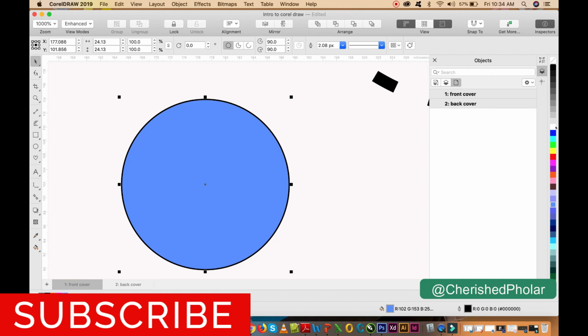If I want to change the color of the borderline, I come on the particular color I want, remember that this is being highlighted, then I'm going to right click. I want to change that black line to red, so I right click and then come here, set outline color. Okay, so I have it as red.